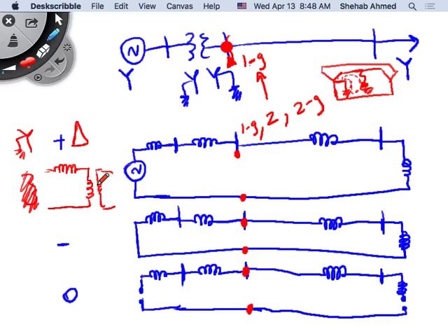Yeah, but here they don't consider phase shift. But if you're going to consider phase shift, you do what we did before, right? I mean, it's the series impedance. In there, what is it in the positive sequence? It's only a series impedance, correct? So if you ignore the transformer phase shift, it's a series impedance like this. If you consider transformer phase shift, you have to include this, and this is the star side e to the j30 to 1, right?